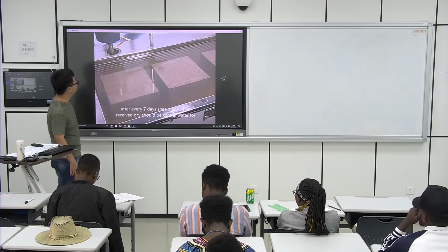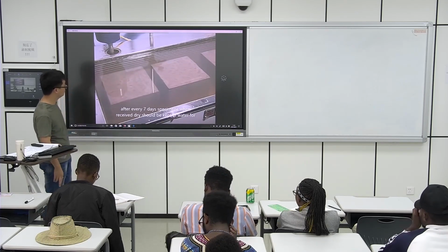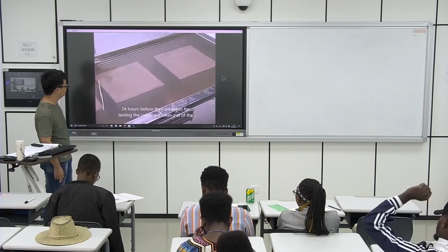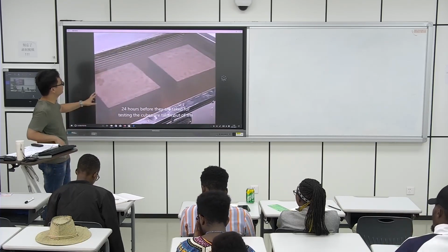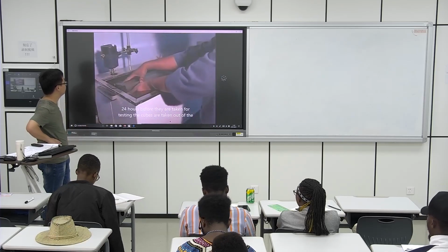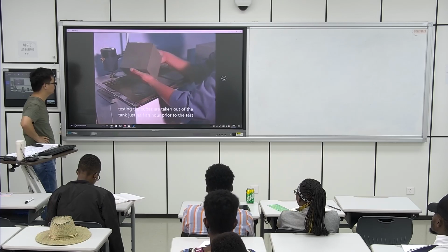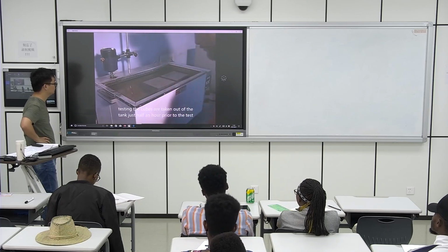Specimens, when received dry, should be kept in water for 24 hours before they are taken for testing. Some details of the process: the cubes are taken out of the tank just half an hour prior to the test.